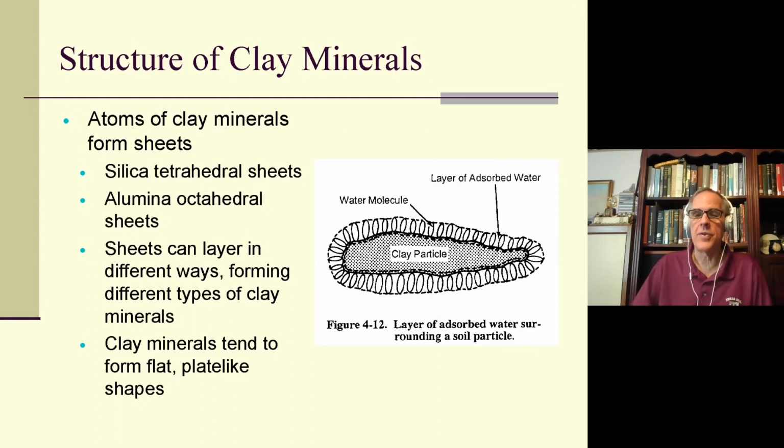When you get into very small particles, we get the structure of clay minerals. Cohesionless soils don't adhere to each other chemically. They don't have a chemical bond. You'll get apparent cohesion every now and then, but usually that's not very important. Atoms of clay minerals form, and in cohesive soils you do have a clay bond.